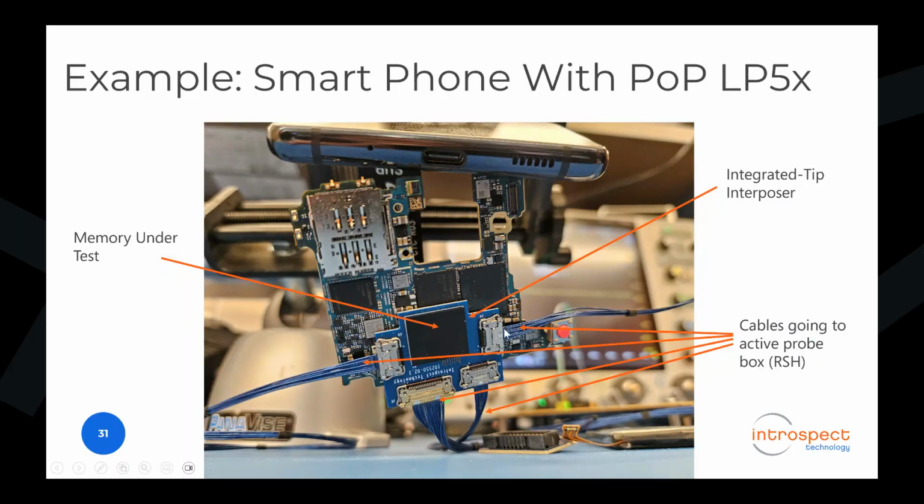It's a controlled impedance microcoaxial cable that gets connected to the interposer through a connector. And we can get away with doing that because the resistors, like I said, are underneath the memory and not at the edge. So we eliminate the soldering part. You still solder the interposer, which is necessary, I guess, in general, but then you eliminate having to solder probes on the interposer. You just simply connect the microcoax cable assemblies into the interposer.